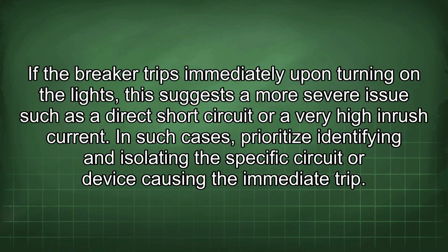If the breaker trips immediately upon turning on the lights, this suggests a more severe issue such as a direct short circuit or a very high inrush current. In such cases, prioritize identifying and isolating the specific circuit or device causing the immediate trip.